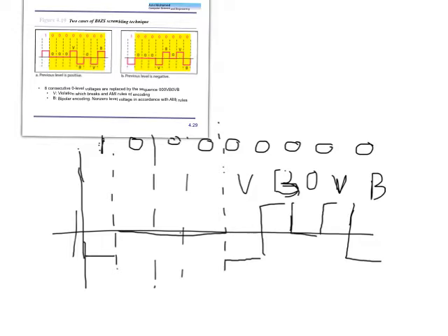So the reception is better in terms of performance, and I did not create any kind of confusion by interpreting some of the zeros as ones or the other way around. Okay. So here I use the notion that if I have ones, I have to toggle the voltage level of the previous non-zero voltage, right? So by incorporating this violation concept, I was able to enhance the synchronization. It's a very simple idea.